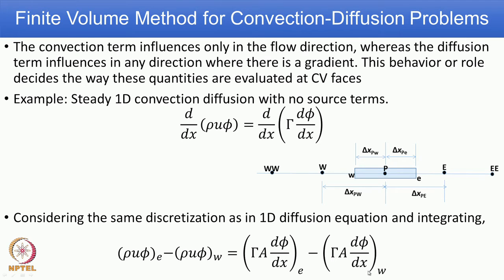So, you understand we have additional complexity when we deal with the convection term. If this convection is written for, say, u as the variable for phi, then it becomes rho u times u, with rho u evaluated at the east face and west face.